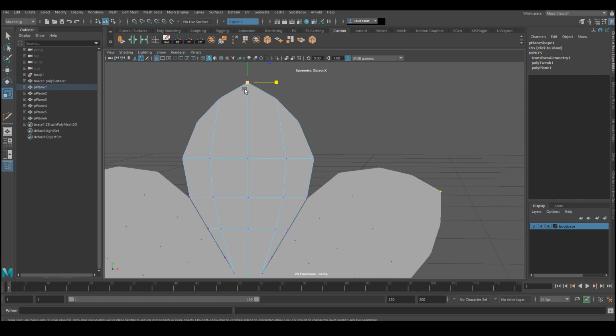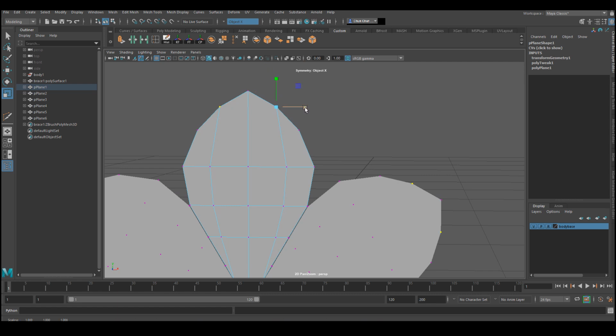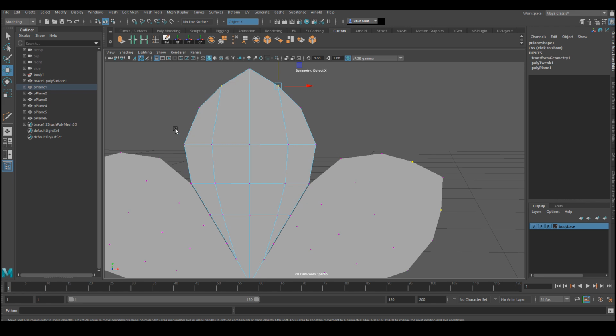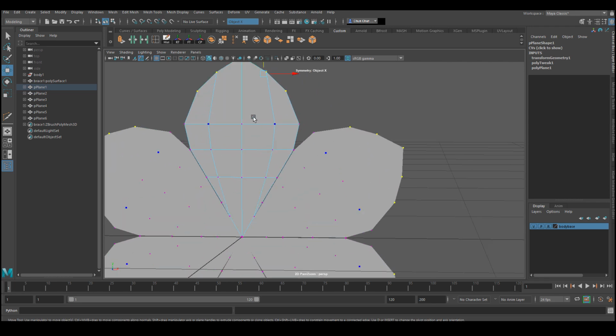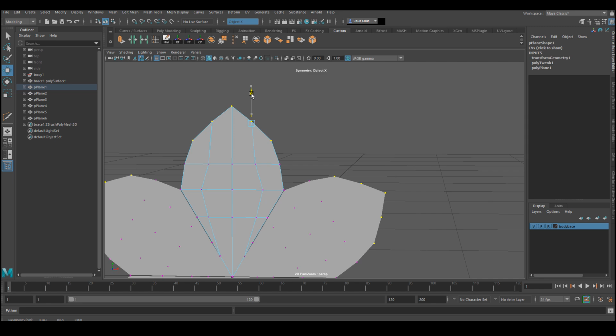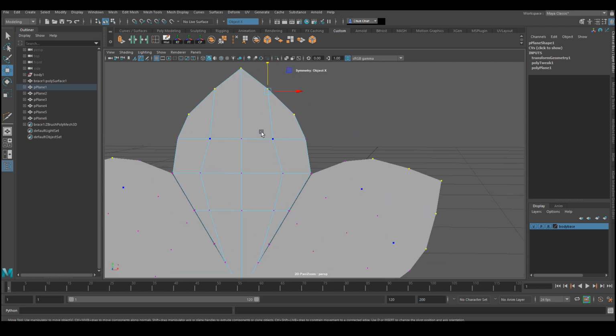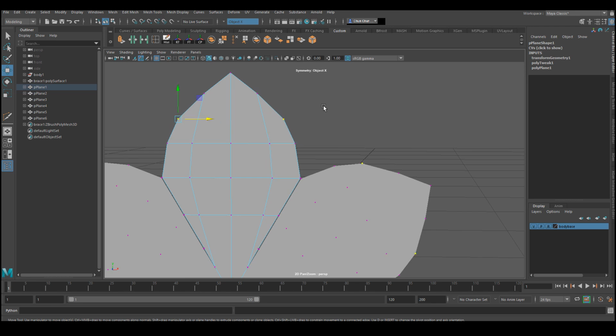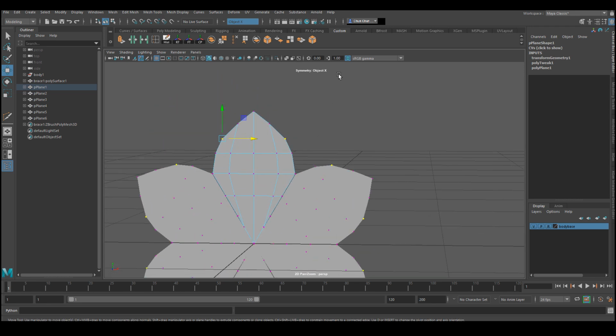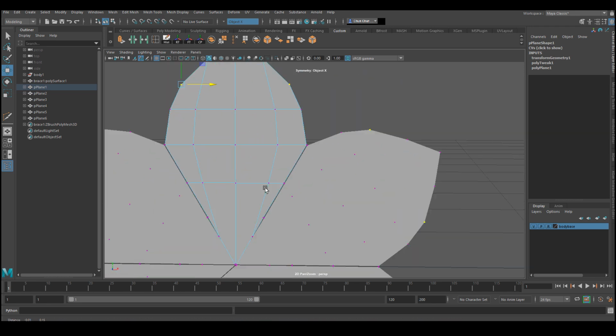When you use duplicate special, duplicate it as instances instead of copies, so that when you're adjusting one petal, you will be adjusting all the petals at the same time. After creating the initial petal shape, I wouldn't know what the entire flower will look like until I duplicate them around the center. So it is very beneficial that afterwards I can still adjust each petal to get the flower shape closer to what I have in mind.